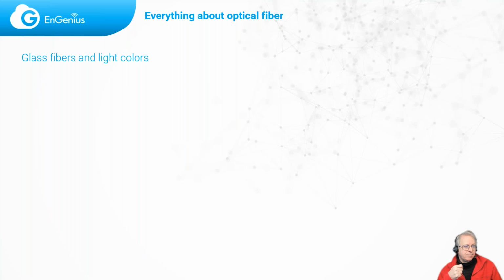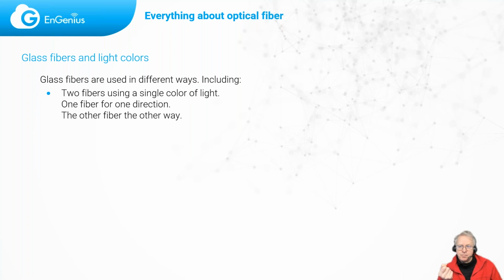So glass fibers are used in different ways. We have them used as pairs with a single color of light. One fiber for one direction and the other fiber for the other direction. We also see that used as one fiber with different colors of light, and then one color is used for transmitting on one side and receiving on the other side, and the other color is used the other way.